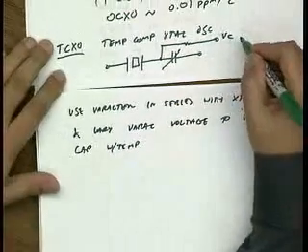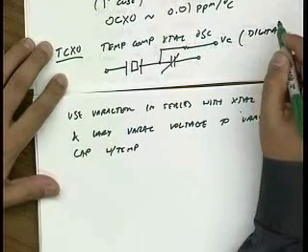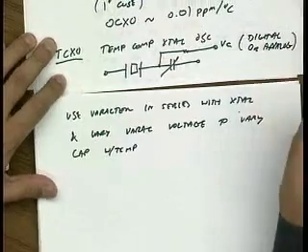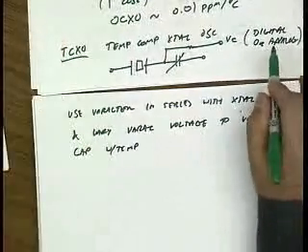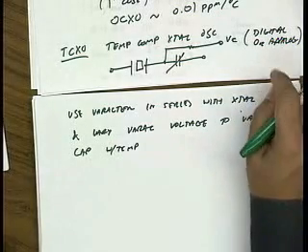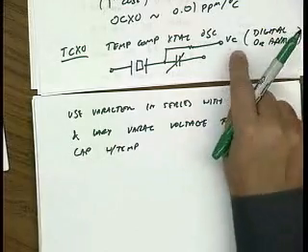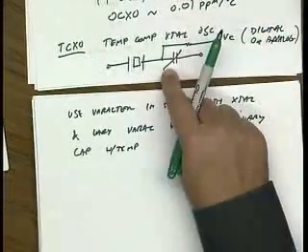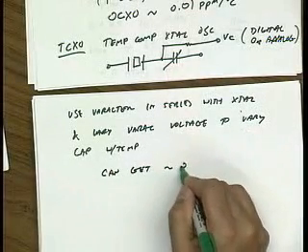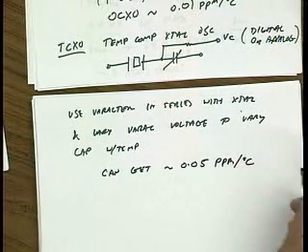And so the voltage here might be digital or analog. More likely it's probably a lookup table. So you have a temperature detector on chip. It detects a local temperature, looks up in a table and says, okay, I need a voltage of 0.7 volts for this temperature to compensate. And at the end of the day, you can get pretty good compensation on the order of 0.05 parts per million per degree C.